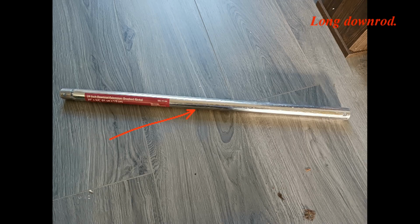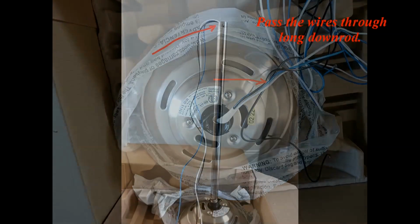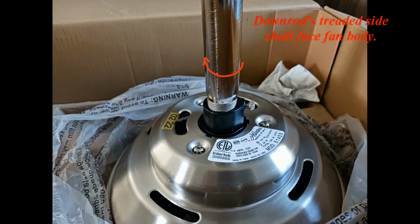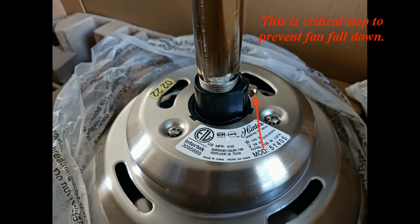Long downrod. Remove the red warning label. Loosen the security screw so the fan rod thread is free of this screw. Pass the wires through the long downrod. The downrod's threaded side shall face the fan body. Screw the downrod into the fan body thread until tight, at least 4 to 5 full turns. Tighten the security screw using an adjustable wrench or pliers. This is a critical step to prevent the fan from falling down.